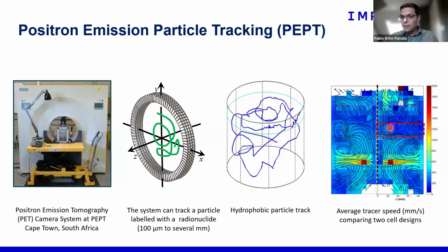So having that retrofit design, in this dashed red rectangle here, shows that the loops that you see in these streamlines are actually compressed in the flotation cell. You can see one loop here, another here, that is typical of these types of stirred systems. The retrofit design not only compresses those loops, but we can see that the tracer particle, the valuable mineral, has a clearer path towards the interface, and that eventually helps the reporting to the interface.